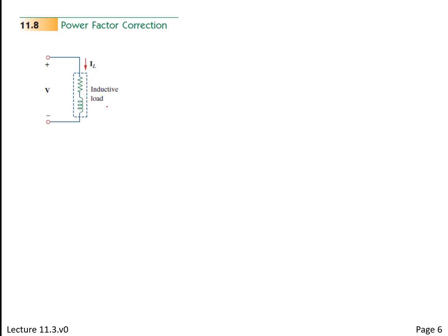The transformer's kind of there, and it's nothing but a coil, right? There's the inductor. But because there's a lot of wire, we know from earlier courses there's a bunch of resistance. It's very hard to make an inductor that has no resistance, okay? So the two always kind of go together, and you hope it's mostly inductance when you're making motors, because too much resistance is just going to make the motor hot. You've got enough heat being generated by friction and rotation and all that anyway. But this is a really typical load on a power source.